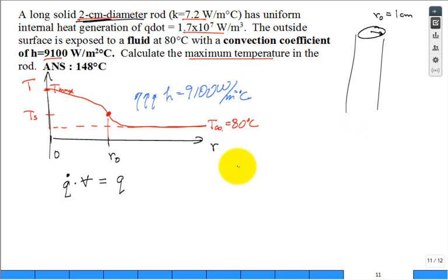So the volume, Q dot times the volume, is going to be pi R naught squared times L. And I like to just say L is picked to be 1 meter. Or you can divide over and then everything's per unit length. All right? So this will cough up how many watts have to get off of the surface and into the fluid.